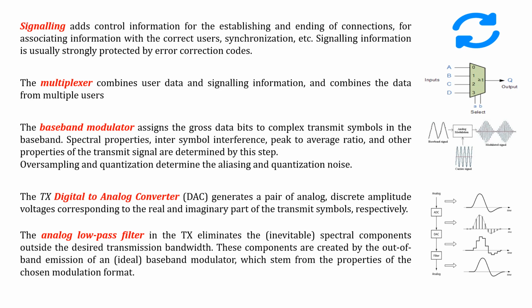There are a variety of modulation techniques available. We can use any one of them in order to make the signals travel over long distances. However, high frequency signals cannot travel over long distances, but we still take up modulation because of design factors. If we use low frequency signals for transmission, then the antennas have to be designed at larger sizes. Sending the signals using high frequency will eventually reduce the size of the antennas. That is the reason why we modulate the signals here. There are several versions of modulation available, which will be seen in later videos.